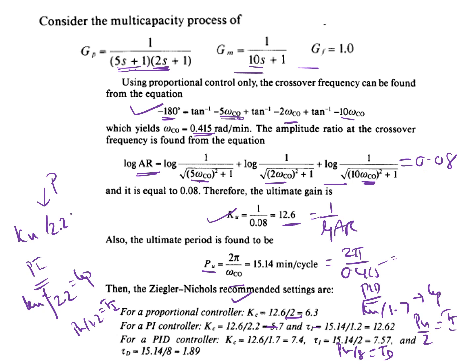Once the controller is chosen, then we have to tune the parameters. Okay, so to tune the parameters, we have three different methods. One is PRC, that is process reaction curve method, which is devised by Cohen and Coon. So it is fully semi-empirical formulas. So for this, the condition is the test should be conducted on open loop basis. Get the parameters like capital A, tau, and TD. Substitute this and get the controller parameters, and substitute in the PID controller block and check the response.